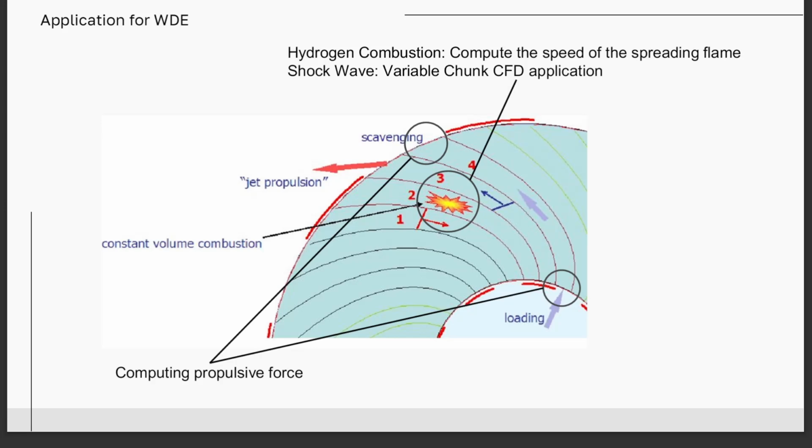Therefore, to analyze it, the wave analysis should be applied to the chunk dynamics, making it easier to capture the effect of the reflection. If the chunk shape is represented with the cross-sectional area of the channel, it can be analyzed in the same way used in the shock tube problem.